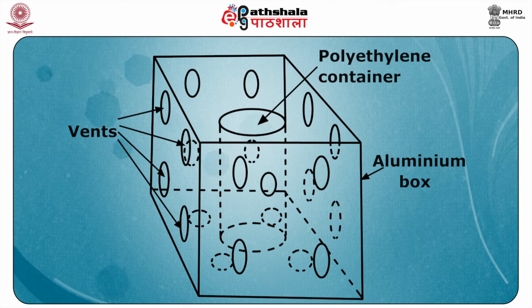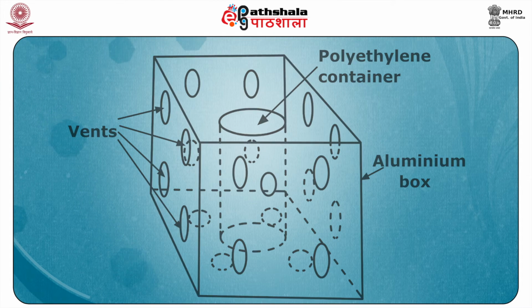In very cold places, a volatile antifreeze like isopropanol is added to the dust collector so as to avoid the freezing of rainwater. The aluminium box is placed in an open place. The treatment eliminates any moisture which may have adhered to the collector. The polyethylene cup is then heated for 1 hour and the weight of the particulate in the container is determined.